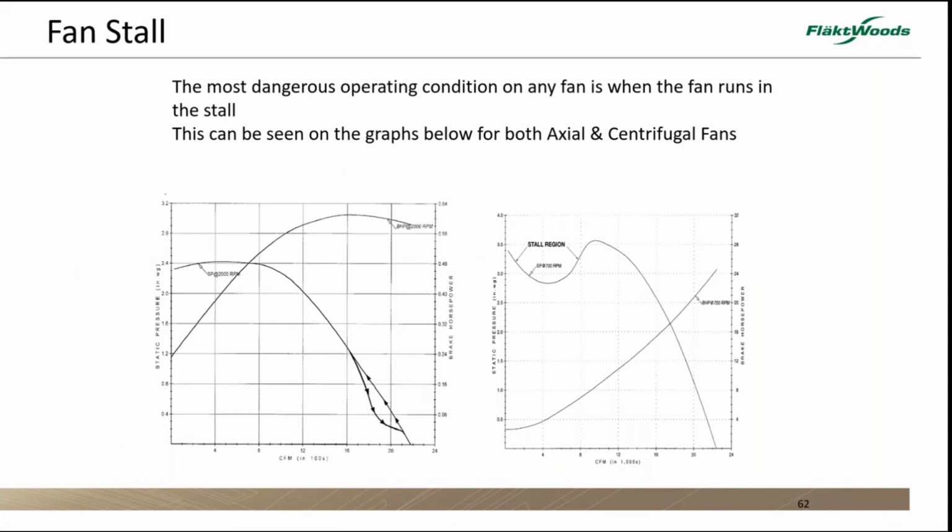But just a couple of things to sort of finish up with, really. Stall is something I'd like you to understand. All fans have potential stall. Centrifugal fans, this is the lower end of the characteristic. So normally you'll see characteristics start off here somewhere. With an axial flow fan, that's at the higher end of the characteristic. And so typically the curves cut off somewhere like this.